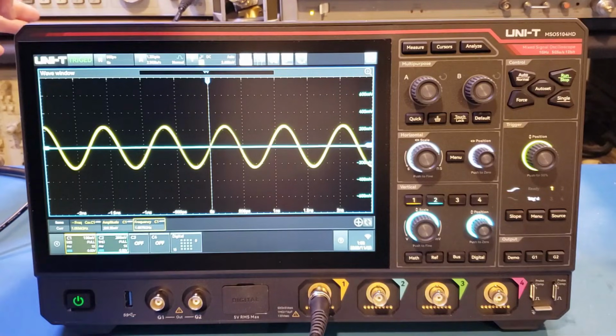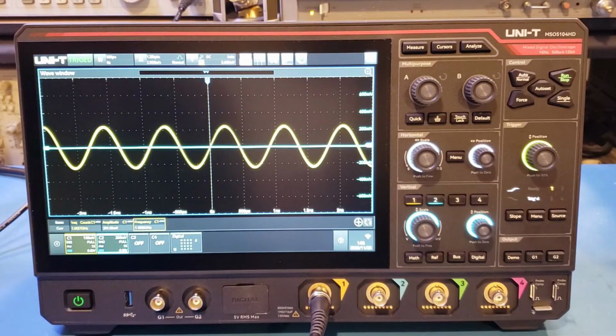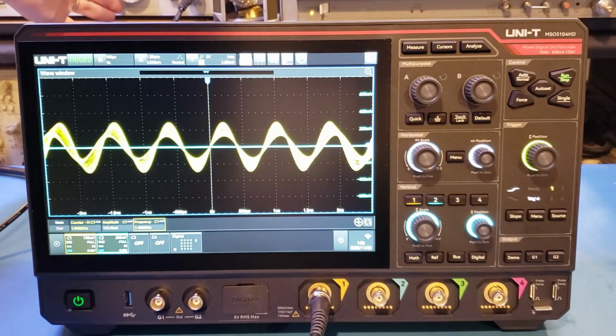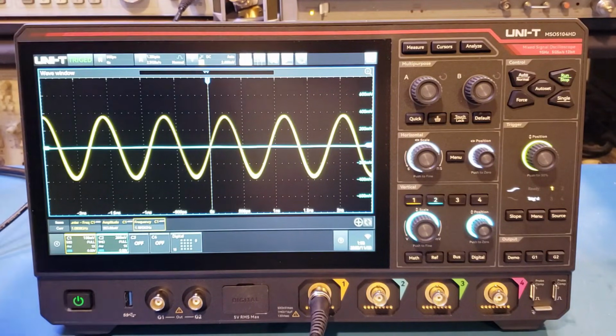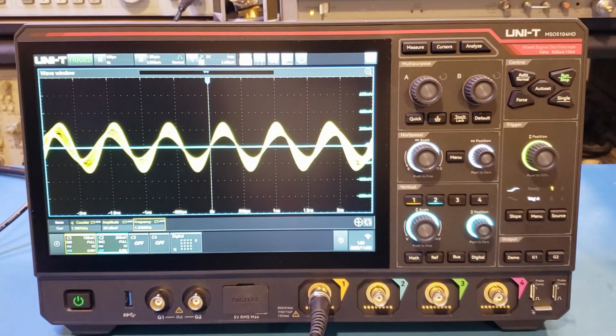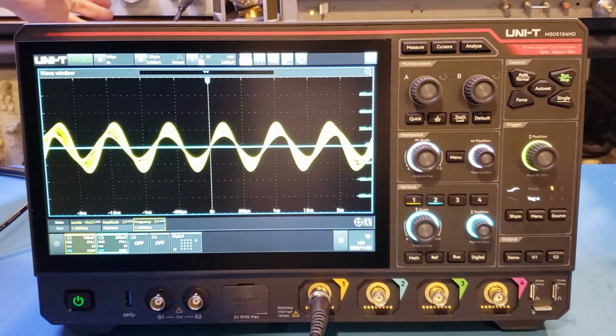So now we're at 1.4 gigahertz, and that's actually still not right. So 1.3, yeah, you can see, okay, 1.2, 1.1, so let's do 1.2. So you can see that essentially anything above 1.1 gigahertz, we're not able to reconstruct, but there's definitely no problem with the 1 gigahertz bandwidth.